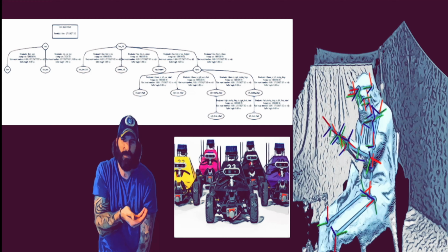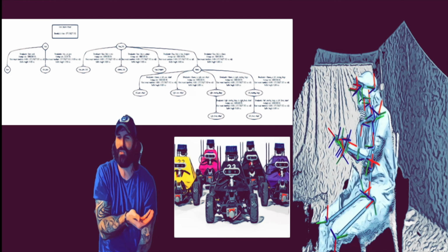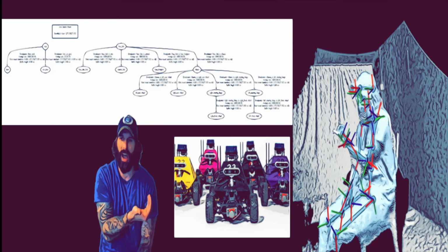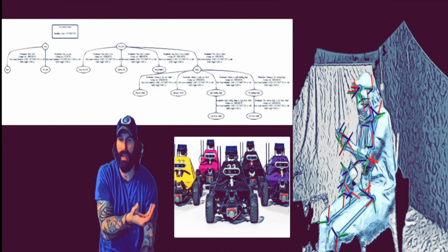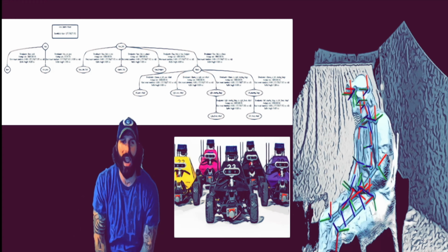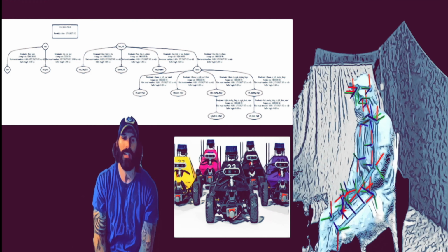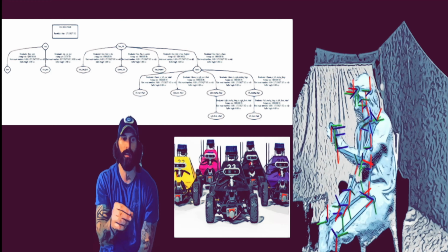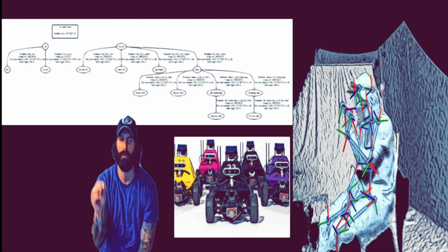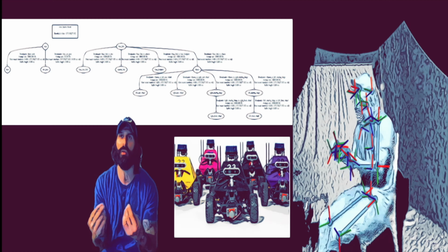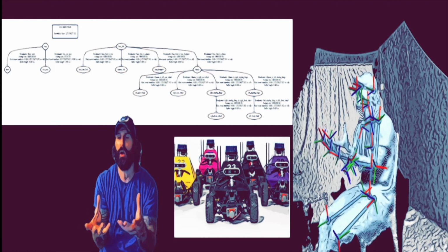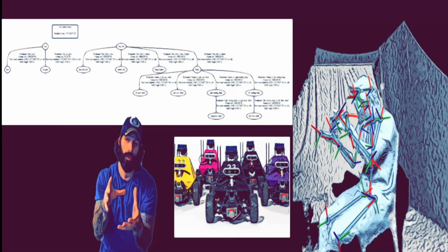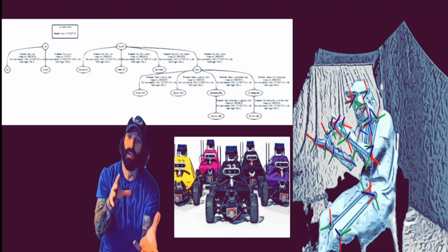I like to visualize a quaternion. There's a couple famous YouTube videos where you're curling your fingers inwards. The IJK, these imaginary dimensions that are run parallel, 90 degrees orthogonal to each other, allow us to understand and compose this one real element and then these three complex elements. So we further understand how these rotations are occurring, but we have to constantly transform these inside our code from quaternion to Euler angle and vice versa all the way back.